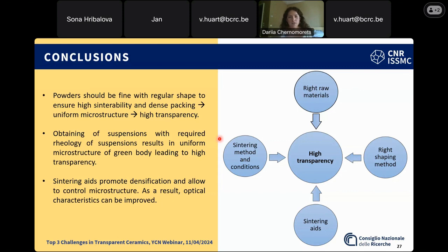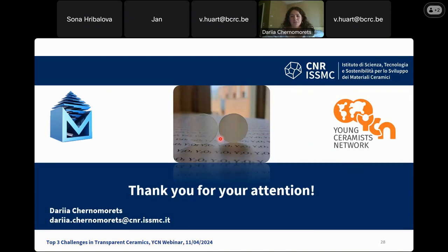Yes, unfortunately, I had quite a lot of issues with it, because specifically my ink dries very fast. So in my case, it's a problem. We try to find a solution by adding some humectant and balancing solid loading and some organics, because again, as always, it's a compromise.